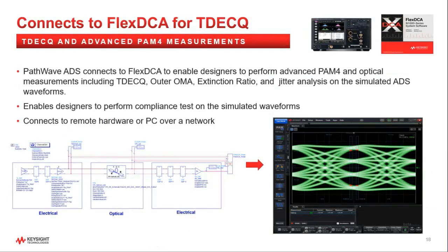Finally, let me talk a little bit more about the FlexDCA for TDECQ. Using the FlexDCA probe, any of the ADS users, including the integrated EOE workflow solution, designers will be able to send the simulated waveform directly to FlexDCA, where they can make all different types of measurements, including the TDECQ, outer OMA, and ER, and so on and so on.